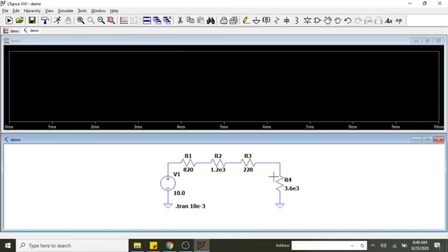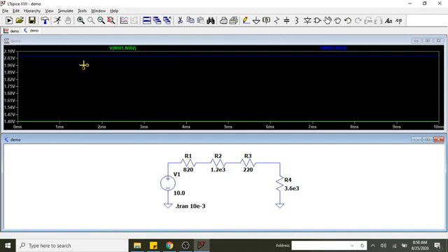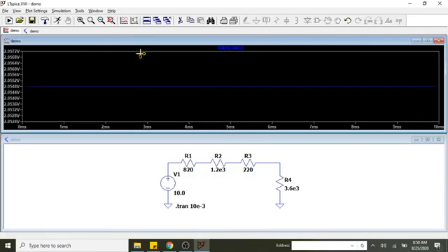What about voltage? So to get the voltage, you need to click and drag. So I'm going to left click on the left side of R1, click and drag, and when the lead becomes black, I'm going to release. So that's showing me about 1.40 volts for our VR1. Let's see what VR2 is. VR2 is the blue, and that's just over 2 volts. And I can go ahead and delete these.